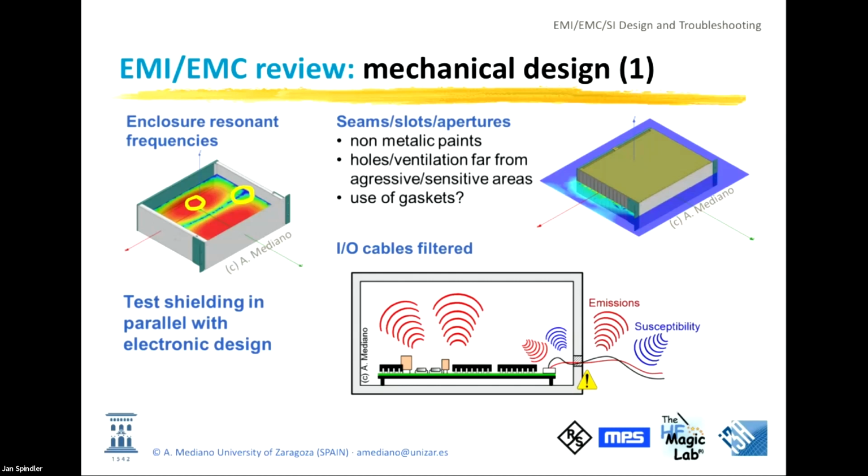There is only one exception, if you have very low frequency magnetic field. That means DC magnetic field, 50, 60 hertz magnetic field, 100 hertz, frequencies lower than 1 kilohertz, and magnetic field, not electric field, then usually you will have problem shielding because this energy is able to go through metal very easily, okay? So you will need to make other solution like rotating the element, or you can introduce some kind of high permeability material like mu metal, nickel, I don't know, depending on your product, no? But in general, the material is not important.